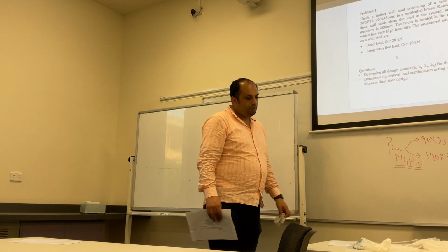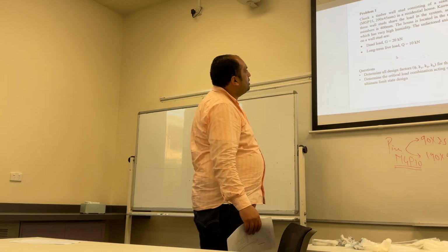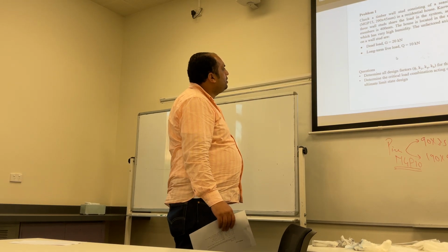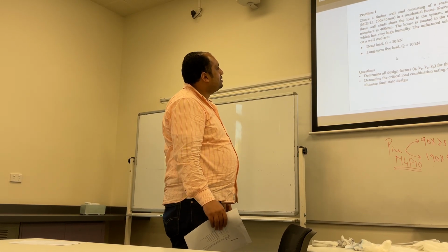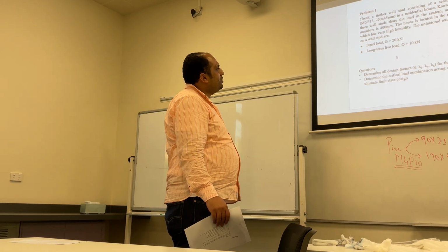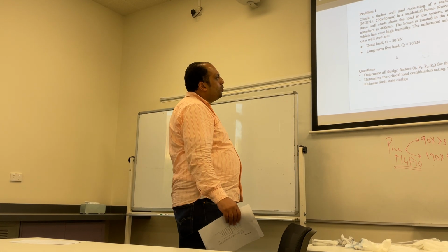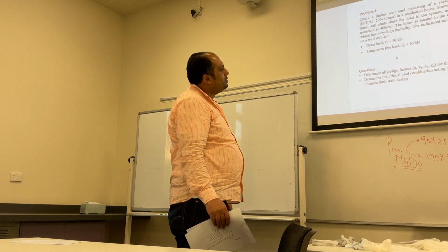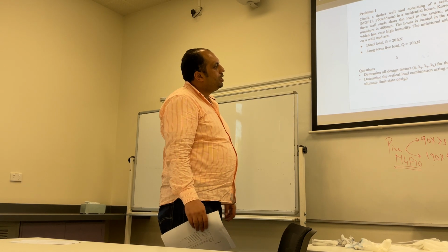So check the timber wall stud consisting of seasoned MGP 15 timber member, and the size of this member is 290 times 45, in a residential house, knowing that the wall stud is 5 meters tall and 3 wall studs share the roof load in the system. So as you can see, the vertical load is shared by the wall studs.